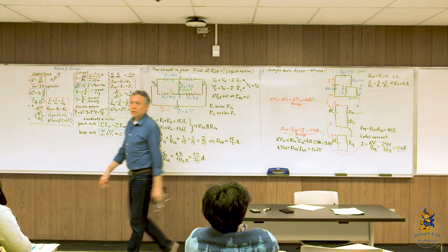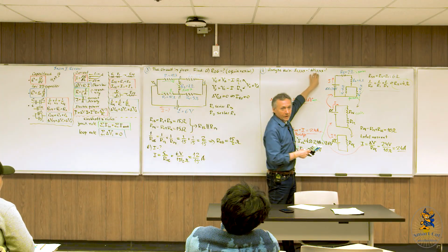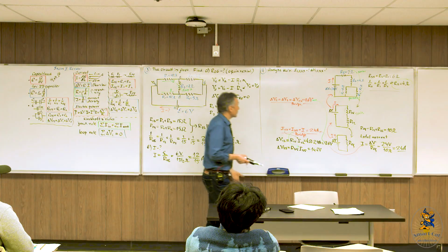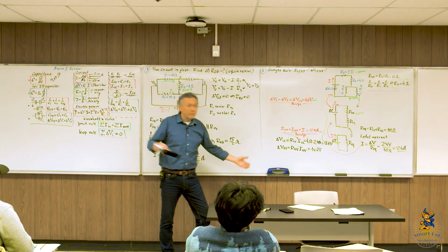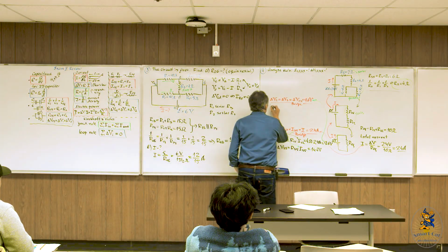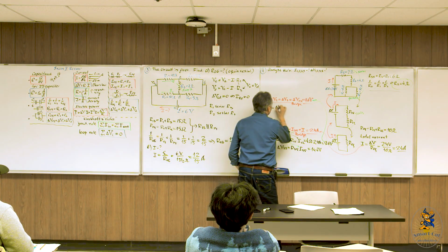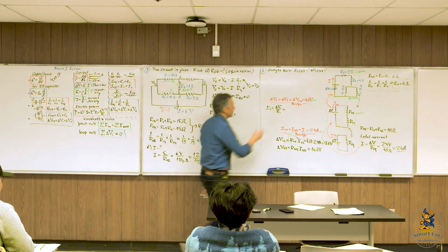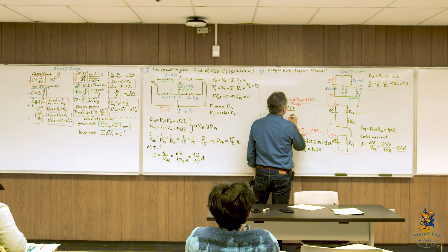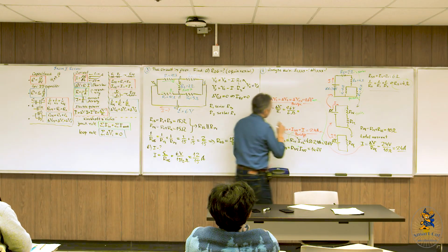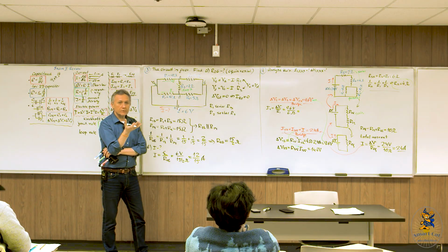And so now we should be able to find two parameters. Actually, we already found delta V1 and delta V2, which are our unknowns, right? So now we should be able to find currents through the first and the second resistor, because resistances are given, potential differences we found. So I1 equals to delta V1 divided by R1. All right, so 9.6 divided by R1 which is 6. It's 1.6, right? 1.6 amps.